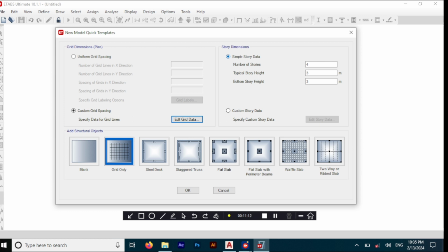Here is story dimensions. When you count your story from the bottom to ground floor, count as one story. Putting column 1 story. Ground up to first, second story. First up to second, third story. Second up to third floor, fourth story. Up to roof, 5 story. So we have to put this one 5.